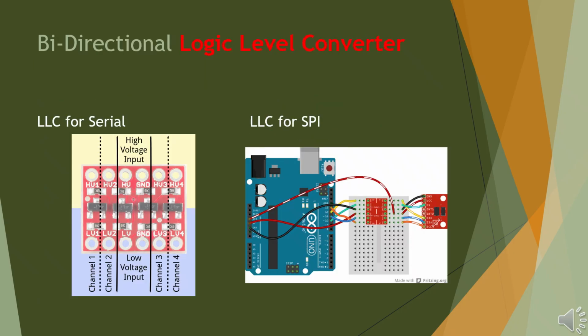When working with microcontrollers and sensors, one of the most critical hardware considerations is voltage compatibility between devices. Different systems operate at different logic levels. For example, an Arduino Uno uses 5-volt TTL logic, while many modern sensors, modules, and microcontrollers like the ESP32 or Raspberry Pi Pico RP2040 use 3.3 volts logic. If a 5-volt device sends a logic high signal directly into a 3.3-volt input, it can exceed the voltage tolerance of that circuit and damage the lower voltage device.